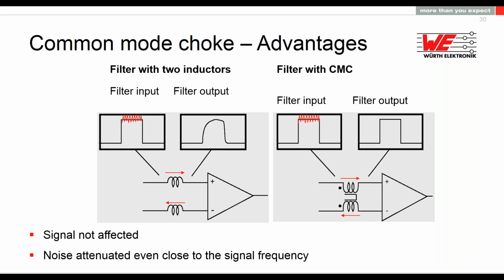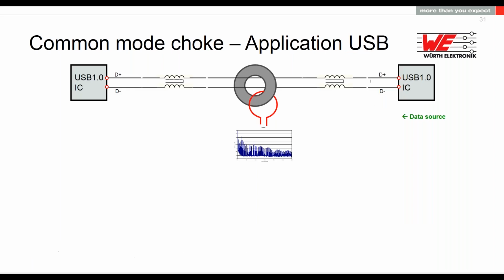If it's a common mode noise, the 10 megahertz signal can go through it. It's not the best ferrite core for 10 megahertz, but it's lossy. With the compensation there won't be that many losses for the signal, but it will eliminate the noise at 11 megahertz, and you don't need an artificial intelligent filter, just an artificial intelligent common mode choke. We should patent that.